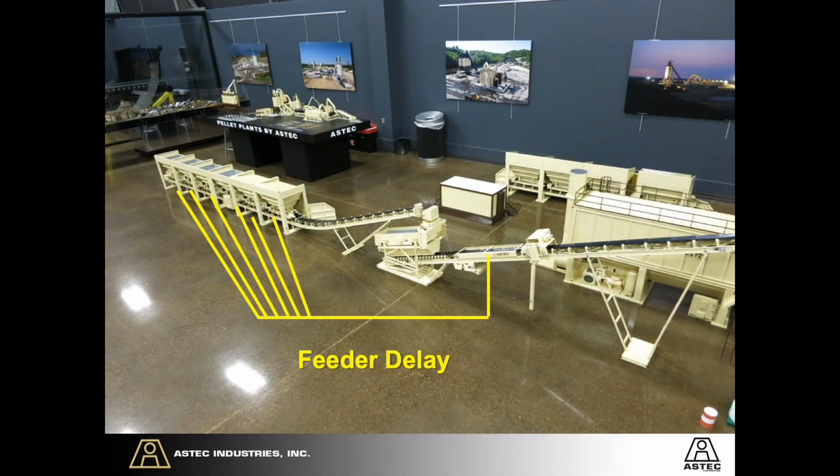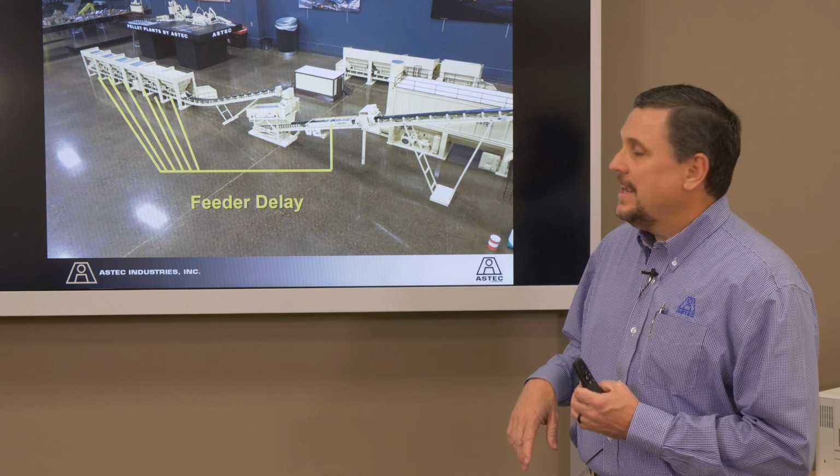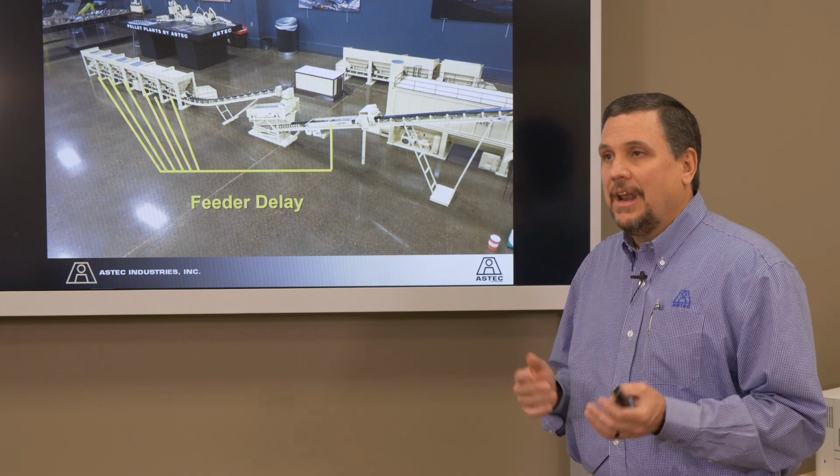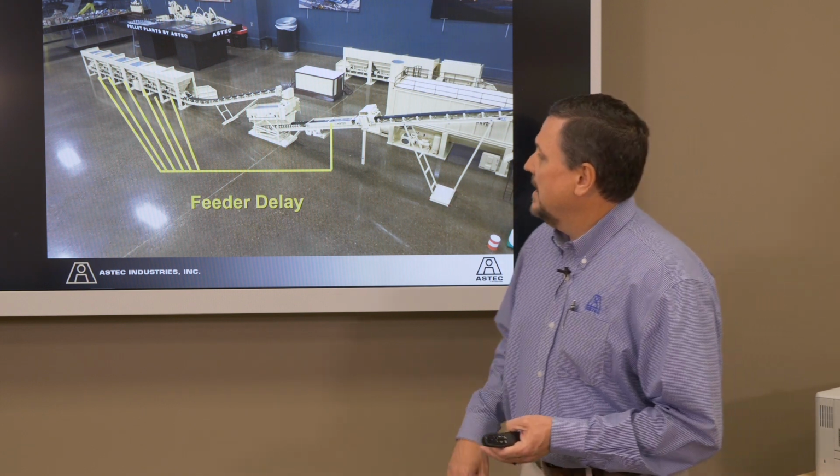As we go back and look at the side view of the plant again, you look at your co-feeds, we talk about feeder delays. We're going to talk about feeder delays and point of mix times a little bit as we move through the presentation. But some people may ask, why are feeder delays important? The reason that feeder delays are important is because they really can cut down on the amount of waste, and it can also increase the quality of your mix. Some manufacturers will call them start-stop times, feeder delays, there's lots of different terms, but they all may mean the same thing.